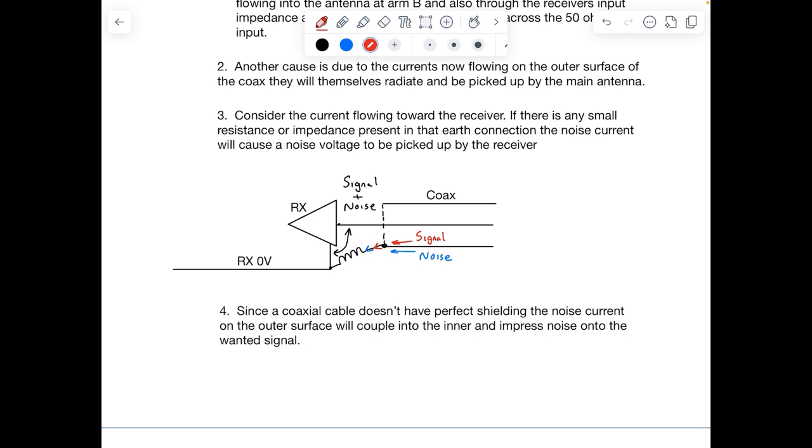Homebrew equipment may well have this issue, but I would imagine most receivers nowadays are very well designed and manufactured and mechanically sound, such that the inductance is limited. So I don't know. I'm guessing it's just a point to bear in mind that there's perhaps a counter argument as to why a choke may not be a good idea at the input to the receiver.